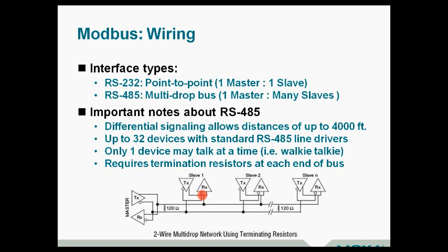Now understand this works a little bit like a shared media. And much like if you've done any RF work, it has a requirement that you have to terminate the ends of your network. So both on your master device as well as the furthest end, we have a termination resistor. Make sure that when you're setting your networks up that you have these installed. And you may also have to do some biasing based upon the specifics of this.